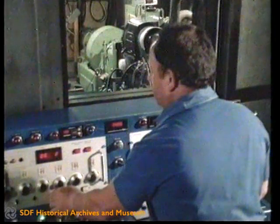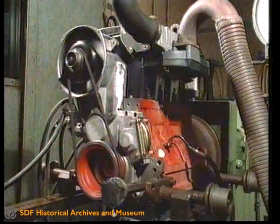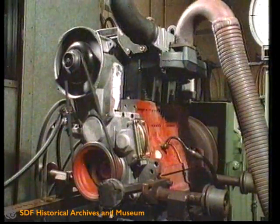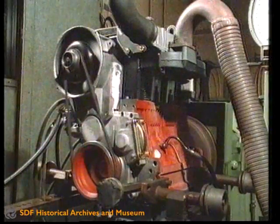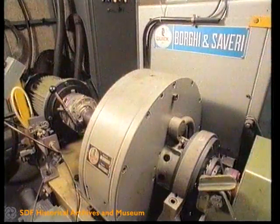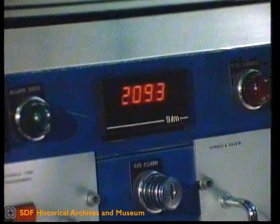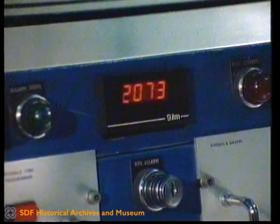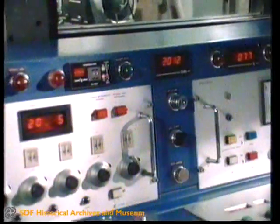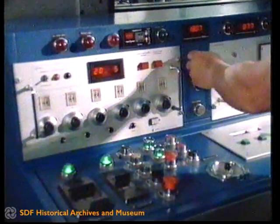Engine torque, output and specific consumption are measured by carrying out engine tests on the bench. The technique used is that of running the engine at maximum fuel feed, at full throttle, and of applying increasing loads to the flywheel by means of suitable brakes. On increasing the load, the revolutions are reduced, and for a certain figure of speed of rotation, measurements are taken of the engine torque and the fuel consumption, from which it is then possible to calculate the output power produced